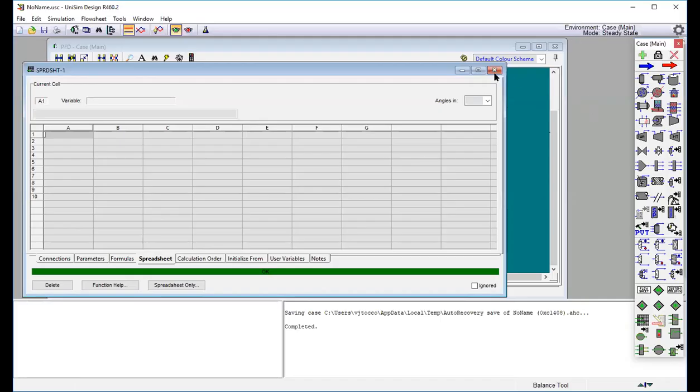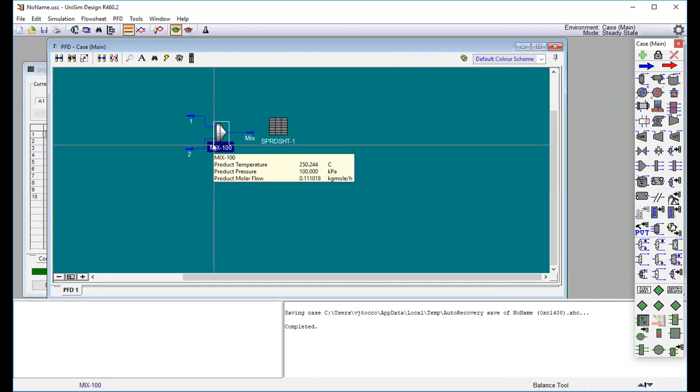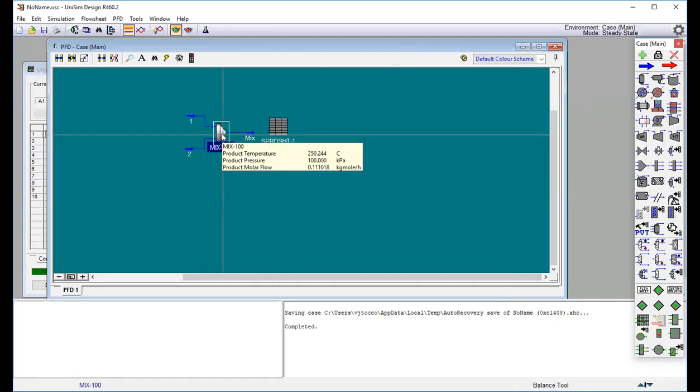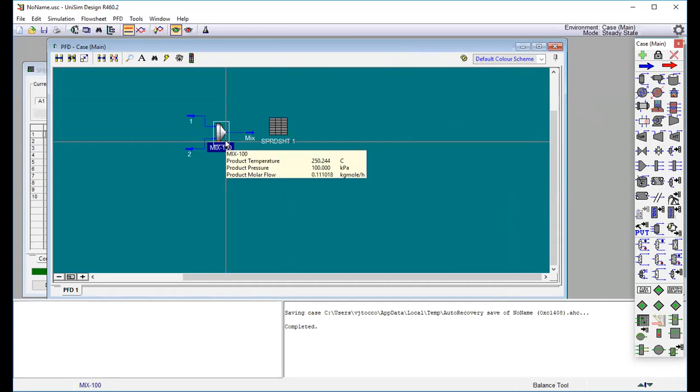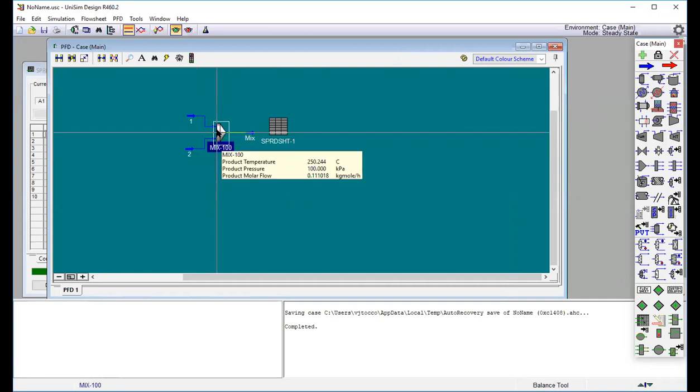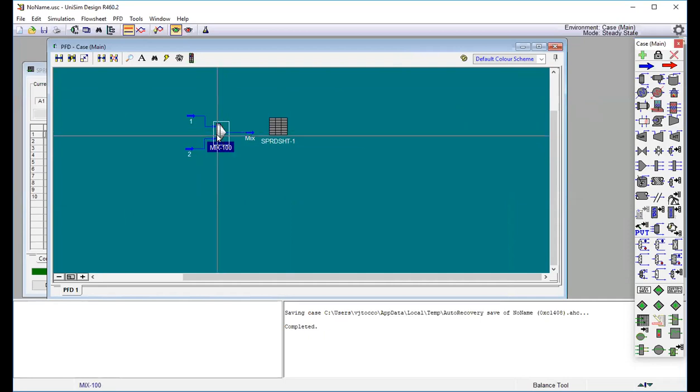I forgot to tell you that it's an adiabatic process. You can determine that it's adiabatic because in the mixer I didn't specify any energy streams, so that tells you that Q and work are equal to 0. So the Q over T term cancels in the entropy balance. I'm going to assume it's steady state, and actually it's not even steady state, right? Because it's just 1 kilogram mixing with 1 kilogram instead of 1 kilogram per hour. So time derivatives are going to go to 0, or in the integrated form, that term would cancel as well.